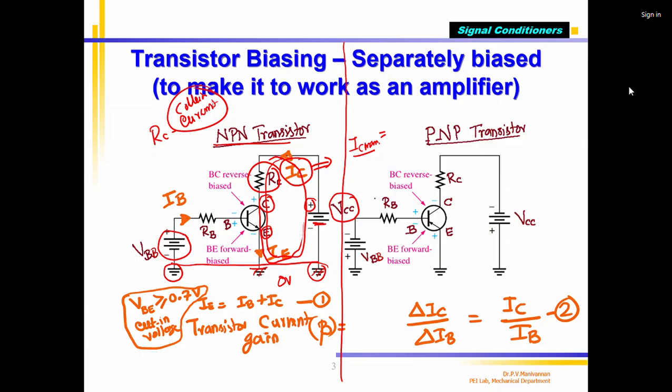Correct? Similarly, as I told you, beta, also called current gain, is decided by the manufacturer. Another important parameter is the VCC collector supply that you are giving between the emitter and collector, which is called VCC max. Note down, these are important parameters. In the data sheet, the manufacturer will tell. Then the next important thing, yesterday I told you VBB max. Then the third one is called IB max, which is nothing but the base current. This current from the VBB power supply passes through the base resistor, called base current limiting, enters the base terminal, comes out at the emitter terminal, and the circuit is closed. Already we discussed it yesterday. I am just saying it quickly for clarity.